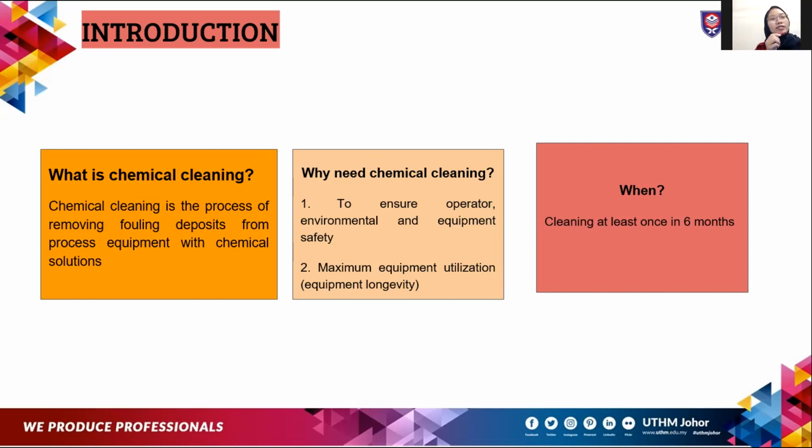These fouling deposits should be removed from time to time to prevent harm and maintain the effectiveness of the process. Why do we need chemical cleaning? We need it to prevent microbial or cross contamination, to ensure operator, environmental and equipment safety, to reduce downtime, and to maximize equipment utilization.